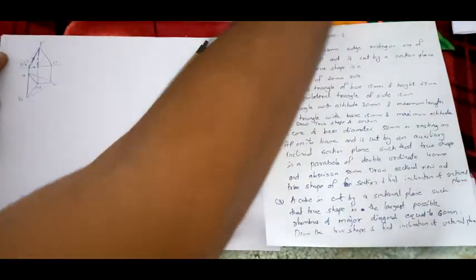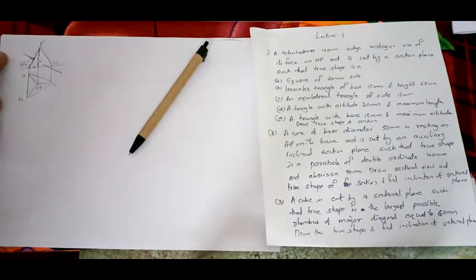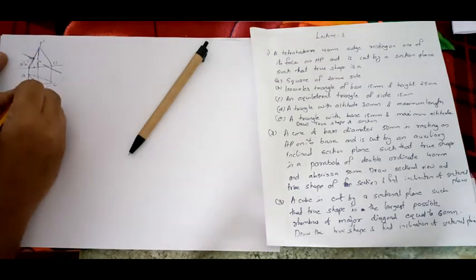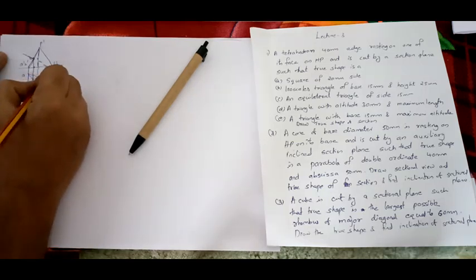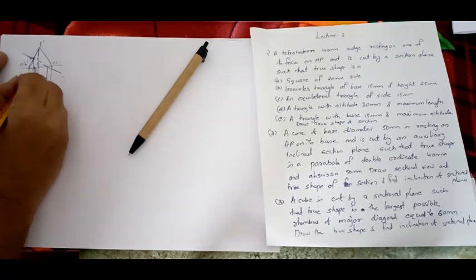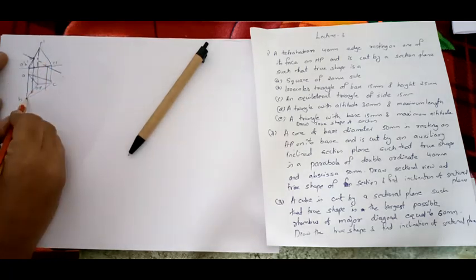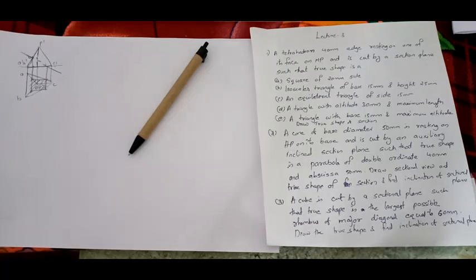See, I will draw the section plane. The section plane will be like this. It is cutting here, on the face, A dash, B dash, so it will cut here and here. Similarly, it is cutting on the base, so it is cutting on AC and BC, and you will get a figure like this. So you will be getting a square and a rectangle. By this type of method you will get a square and a rectangle.